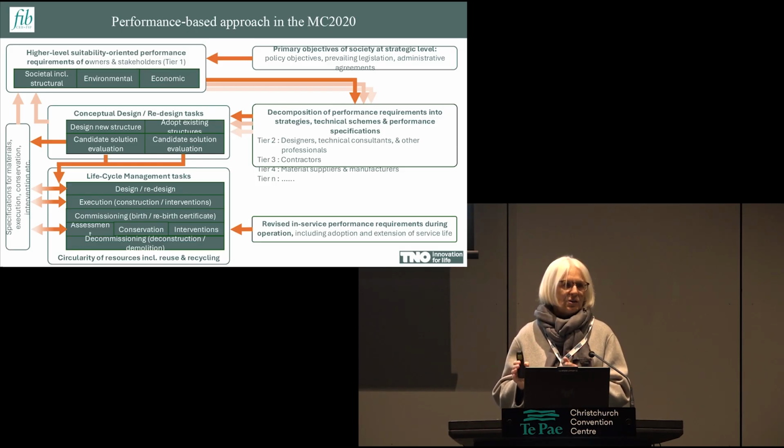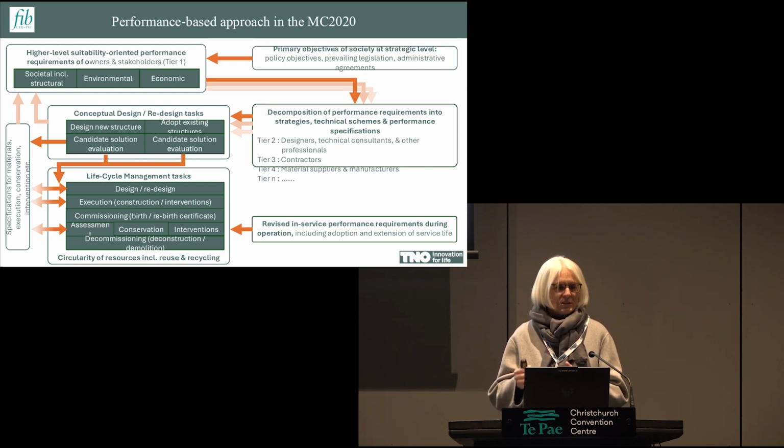We need to communicate with everybody within the chain of parties, expertise involved in order to allow the optimal solution. So communication between material producers about what is feasible and what could deliver that performance is necessary. Communication with the designers, but also designers with the construction experts who can improve parts of the design, providing additional improvements, for instance, with regard to detailing of reinforcement, couplings versus overlapping of rebars. Very practical things, but can really have a huge impact on improving our designs.